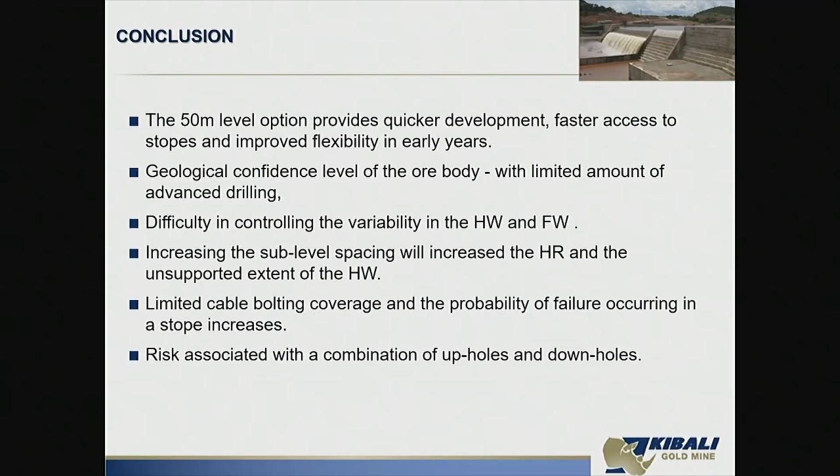So controlling the hanging wall and the footwall would become challenging, especially when you start mining and have something that is not expected. And also, increasing the sublevel increases the hydraulic radius, as I said. And also the unsupported extent of the hanging wall, so the cable bolting becomes not very effective. And also you have some other risk associated with a combination of uphole and downhole.